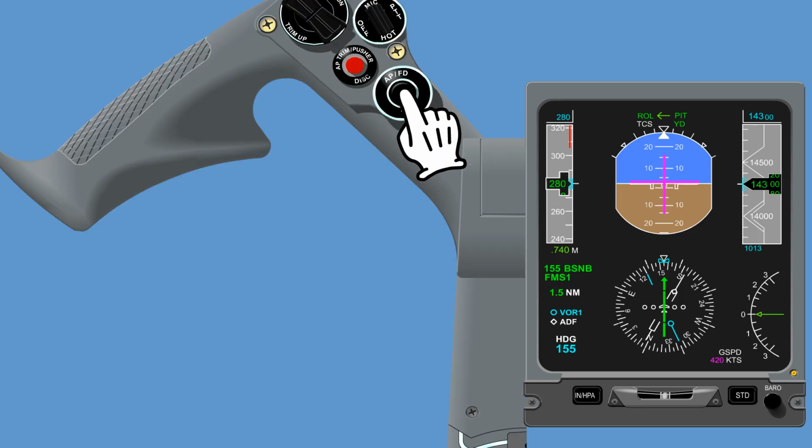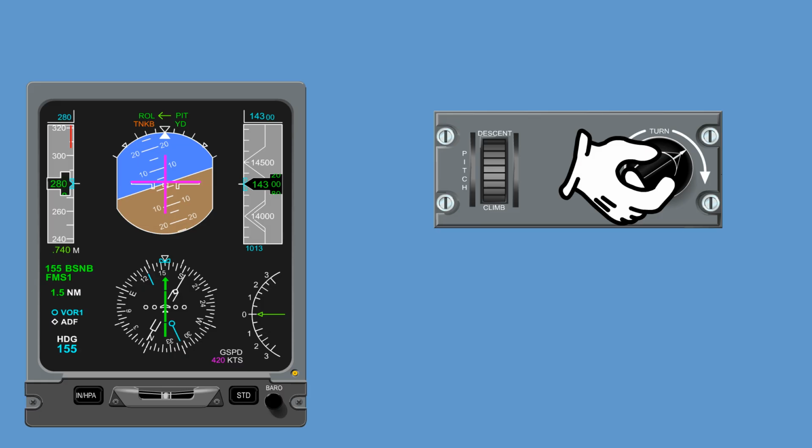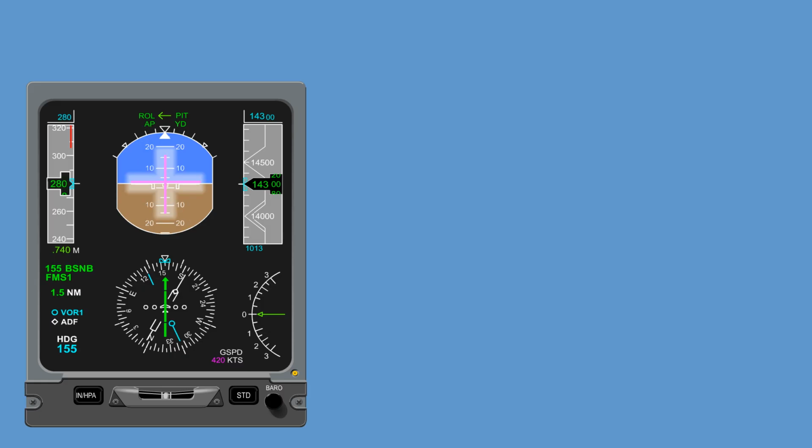The following additional Autoflight information can be seen on the autopilot status field: a TCS legend to indicate that the touch control steering submode is engaged, and a turn knob legend in amber to indicate that the turn control knob is out of detent. Finally, in the center of the attitude sphere, the flight director command bars will be found if selected to on. In case the flight director fails, the command bars will be removed, and instead, a flight director legend is displayed in the mode annunciator area of the primary flight display.